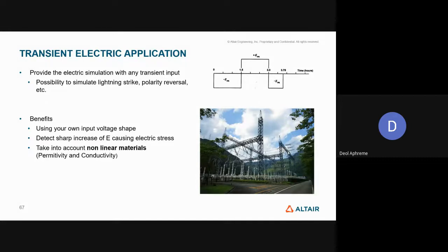So it's important that we simulate and understand the characteristics and what is actually going on between each component, so that we can optimize that component. For example, the number of turns in a transformer is the weak point of a transformer when there is a lightning strike. You can definitely optimize that in the simulation phase itself.